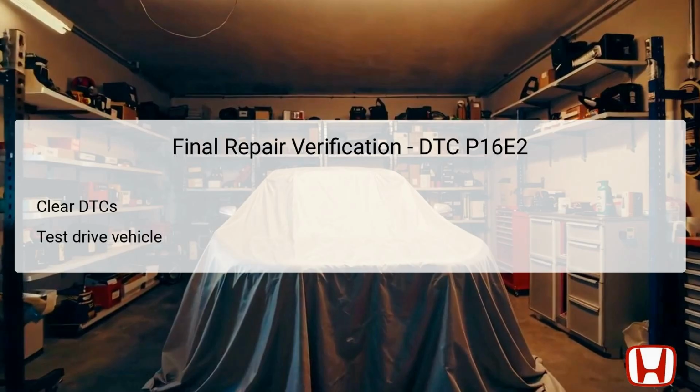After completing the necessary repairs or component replacements, the final verification step entails clearing any stored DTCs from the PCM and conducting a test drive. Clearing the DTCs ensures that any previous codes do not interfere with new diagnostics.